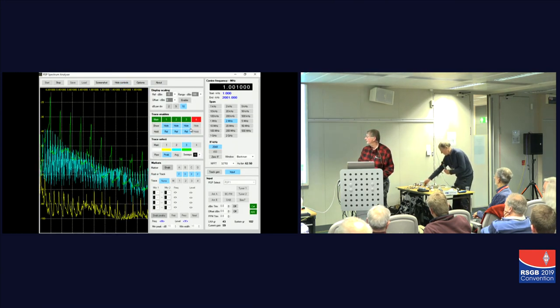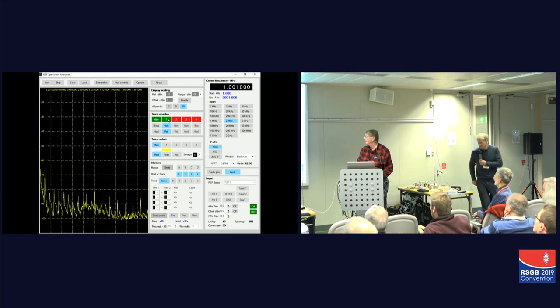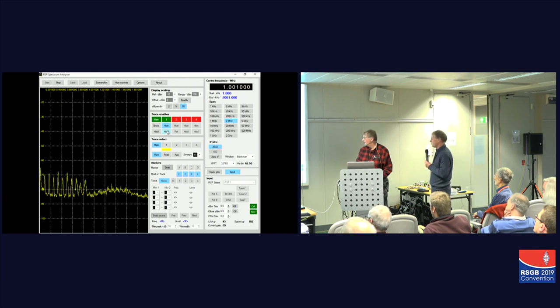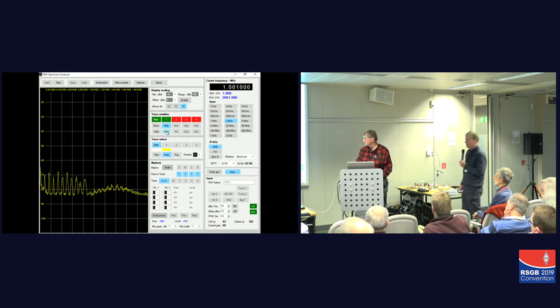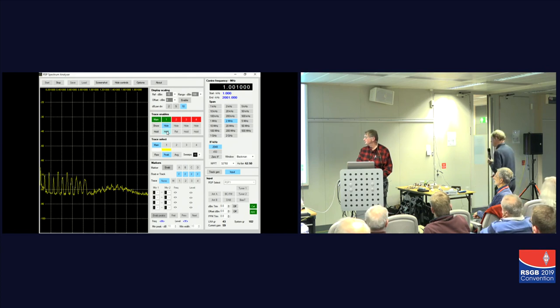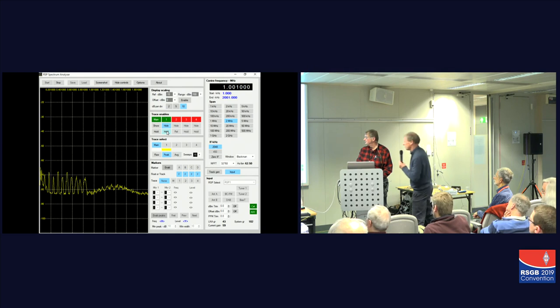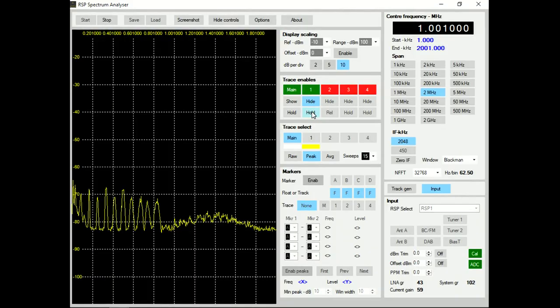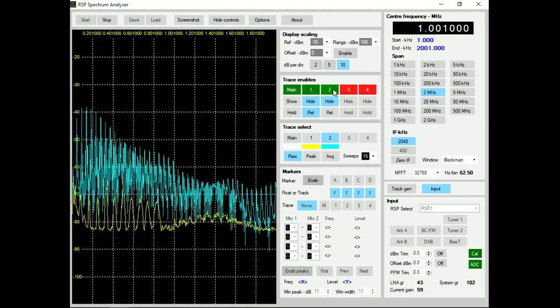Now, this is a USB power supply. So we need a new... Okay. So this is a genuine Apple iPhone charger, with a 1 amp load on it. And we know it's a genuine Apple iPhone charger because if you look in the USB socket, you can see a serial number. So that's down at, what is it, in dBm here, minus 70 dBm. There's 20 dB of attenuation in this LISN. So now look.